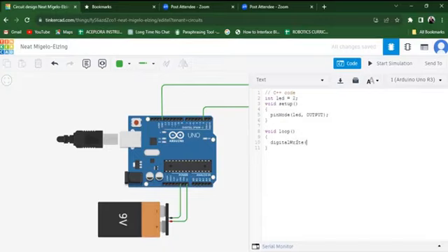In brackets, you put your variable there. What do you want the Arduino to send data to? To the LED. And what do you want the LED to do? You want it to come on. So in Arduino programming language, you use high to turn on a device, right? We say the digital signal has two states, ones and zeros. So if you want to achieve a one state, you use the code language high, to tell it to come on.